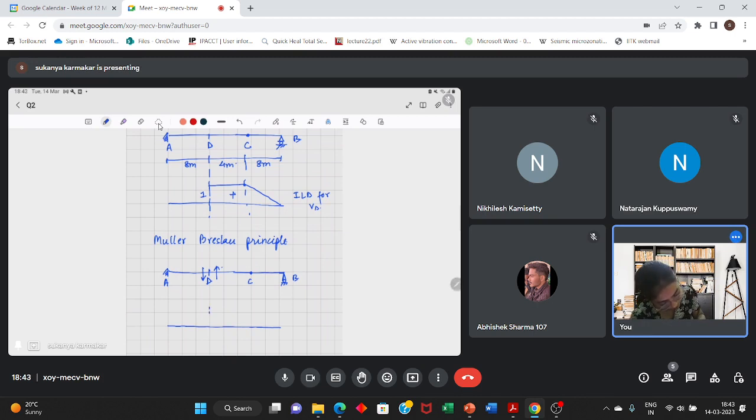So this portion will move up by 1, since the total motion, the sum of both the displacements, should be 1. Since the entire movement is getting concentrated on the right hand side, this will be 1. Now this C point is hinged. So once you push it up, DC will move up straight. Suppose this is hinged, and beyond this another member is there. Once you move this by 1, the entire thing will shift up.